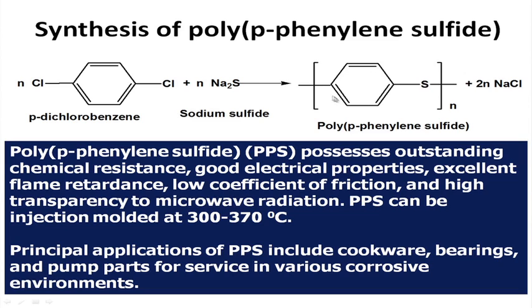So, this polymer is not combustible since the amount of hydrogen is less, it forms char. Char formation occurs at the flame temperature or when it comes in contact with flame, or if there is any fire, this polymer forms a charring effect. So, this fire retardancy effect is observed in the case of polyphenylene sulphide.